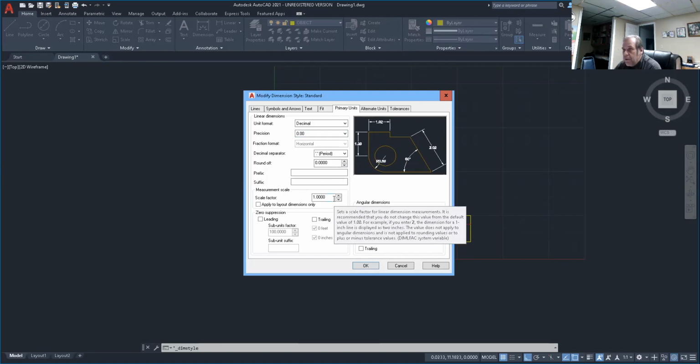Okay, now we can get rid of 0. See the 0 suppression? See that radius 0.80? That's a leading 0. So leading 0, let's suppress it. See where that 0 went away? We're going to keep our trailing 0 because of significant numbers, okay? We can get rid of the leading 0. And here's another one of those scale factors that we'll talk a little bit about later.